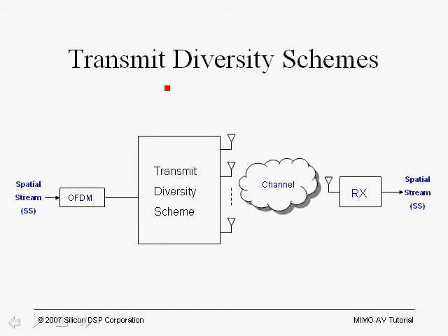The idea behind transmit diversity is that when you have multiple transmit chains, how can we exploit the fact that we have these multiple transmit chains in order to achieve diversity at the receiver? And in many cases, you have receivers with one antenna, like in cellular or ultramobile, in which case it is beneficial to place the diversity at the transmit side and simplify the receiver by only having one receive chain. However, you can have diversity with both transmit diversity and receive diversity, as we will explain.